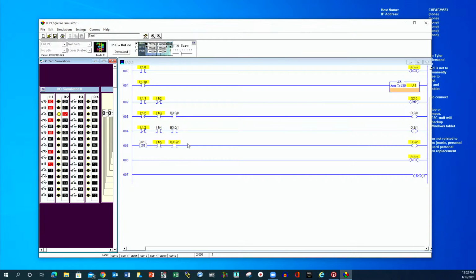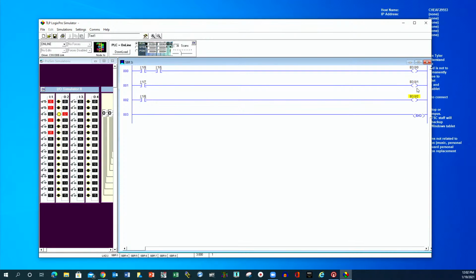So this lives in a subroutine, but now let's go and turn 10 off. This was left on. So if I turn off 8, 8's gone now, but the bit is still active. You kind of see what I'm getting at? Even though I'm not jumping to the subroutine anymore, I told it to stop going to the subroutine. It was in a true state when I left. And since I left, I went ahead and shut off 8. And if we go back to 8, don't forget, this 8 turns on that bit. But because it's not scanning it anymore, it is stuck in this state.